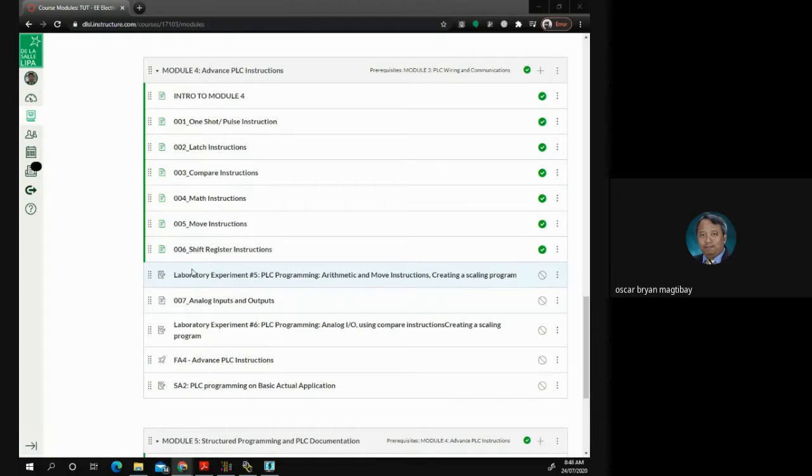So we have many field devices that have analog signals. Number one of which are what we call pressure transducers, flow transducers, level transducers, and temperature transducers. Those are for the input. For the output, it could be either variable speed drives or heaters.